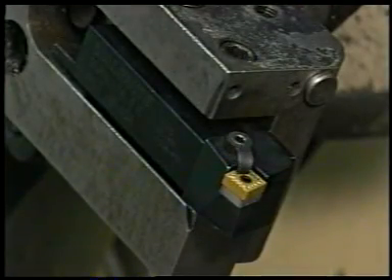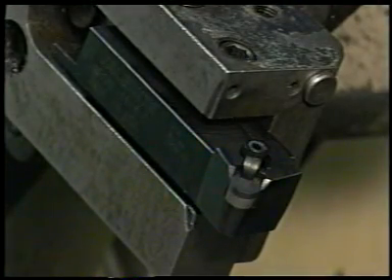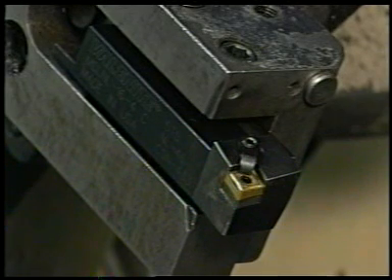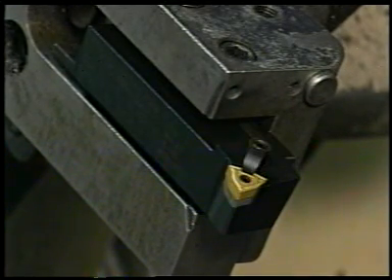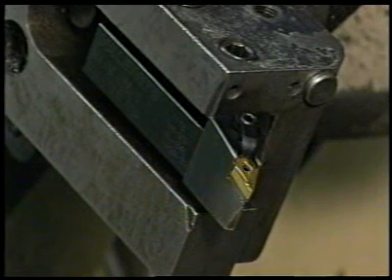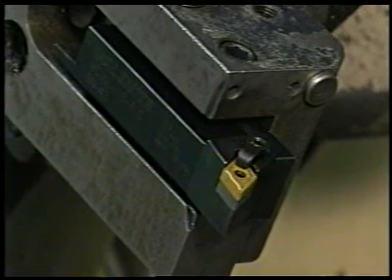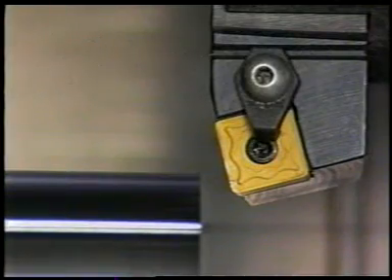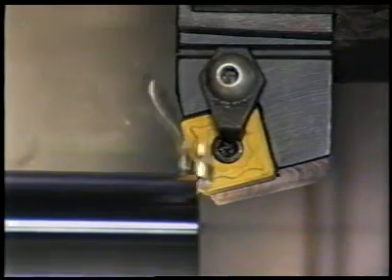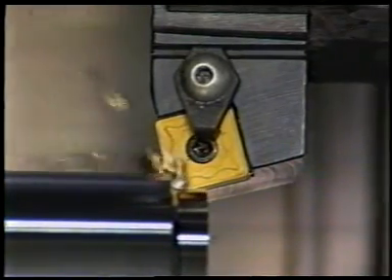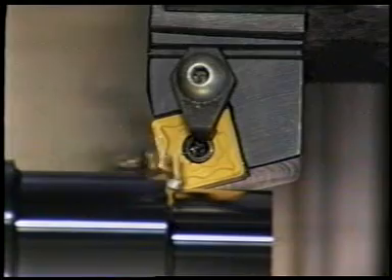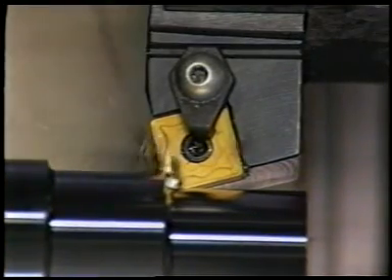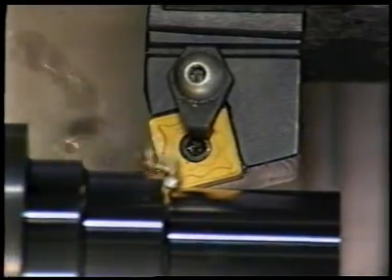Turning tool holder styles are defined by their lead angle and the shank offset. Longitudinal turning, facing, and various contour cutting operations require certain tool holder forms. There are hundreds of styles. In turning, a 15 to 30 degree reverse lead angle tool holder is often used. This style distributes the cutting stresses, thins the chip, and reduces pressure on the edge.